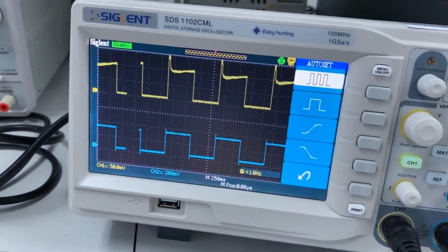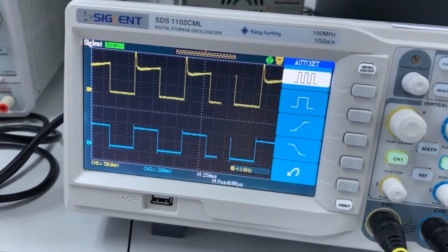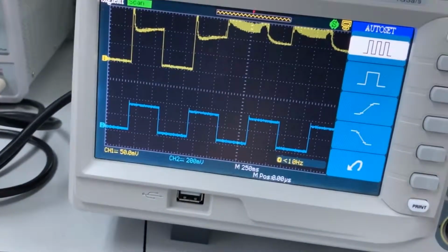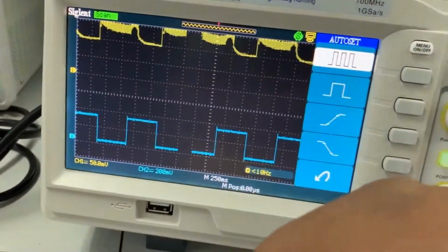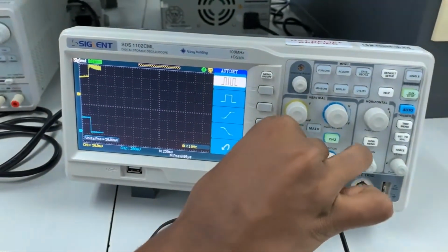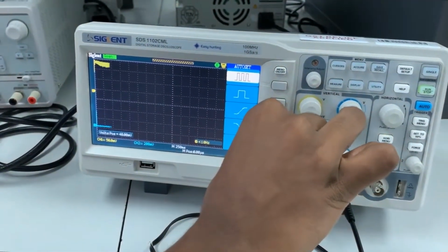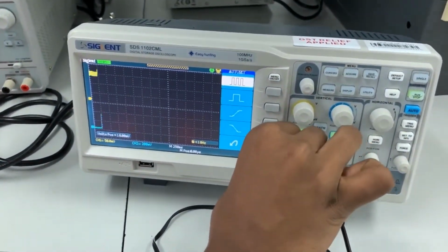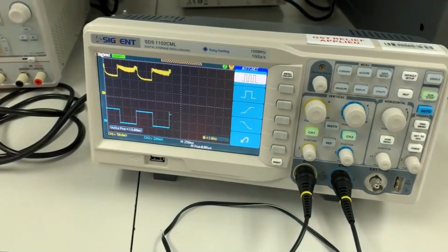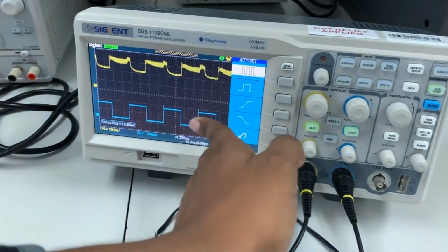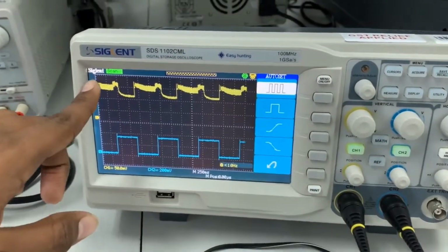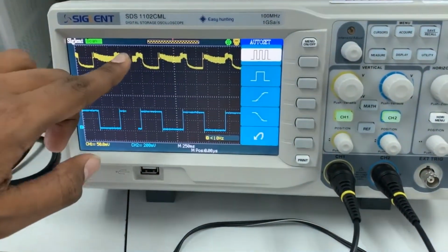Because of the expression of F. Now we're going to inspect the hazard. We're going to turn on both A and C. We're just going to move this to get a clear picture. As you can see here, the input B is at the bottom, so you can see a comparison. What is happening here is the output briefly dips to 0 and then goes back up.